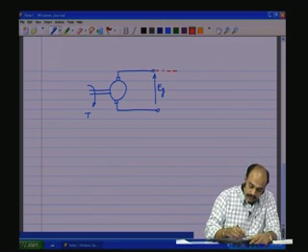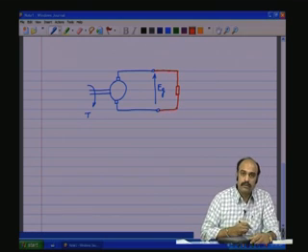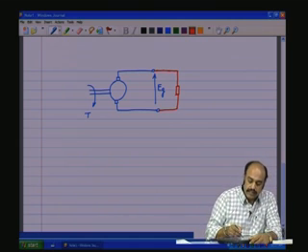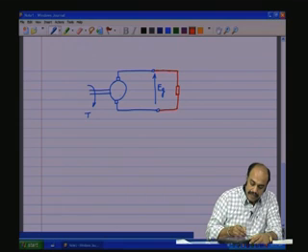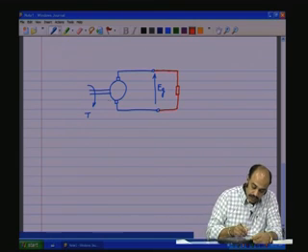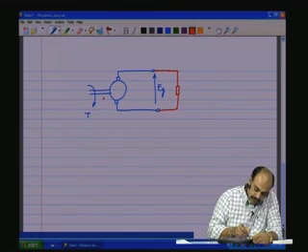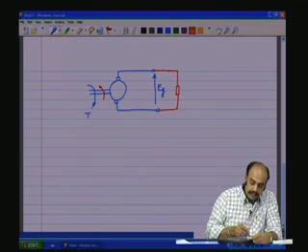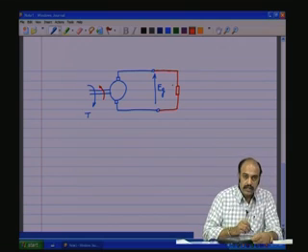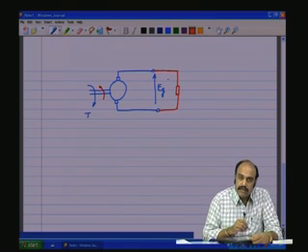Now, if one loads here, that loading effect on the electrical side should percolate back and get reflected on the mechanical side, so that you draw more energy. Any load here should reflect as a reverse torque here, such that the prime mover, whatever is moving the mechanical shaft, should now apply that extra torque to overcome that load and still rotate it at the same RPM, so that you get the same induced EMF E g.